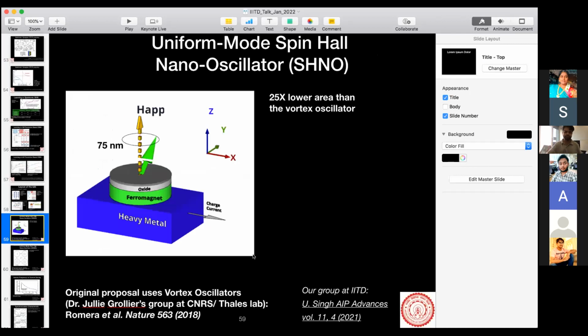Okay. Now let us go into the oscillator-based computer. This is the work I'm actively working on now. So what is an auto oscillator? Let's start with that. It depends on how you want to loosely define these terms. For a long time, what is called an auto oscillator I used to call an oscillator, and what people call a damped oscillator, I used to call a resonator. Either way, you have a differential equation of second order, right? An RLC circuit is a second-order differential equation. But is an RLC circuit an oscillator just by itself?